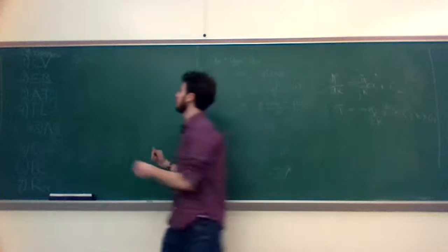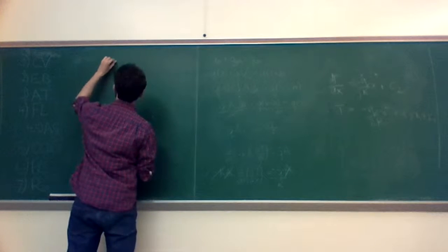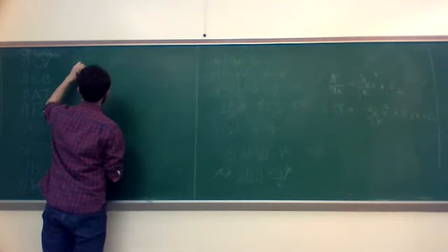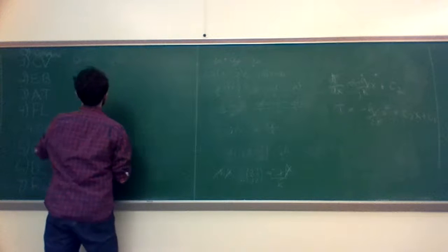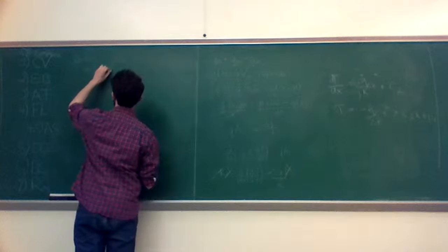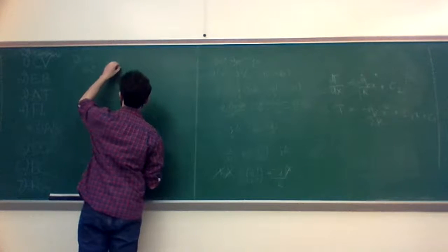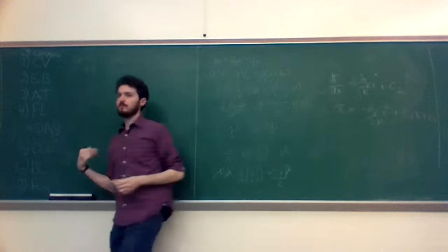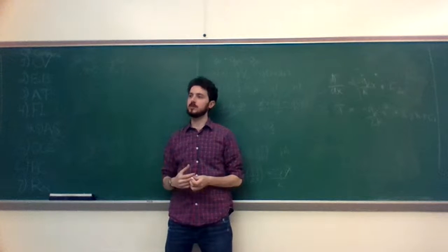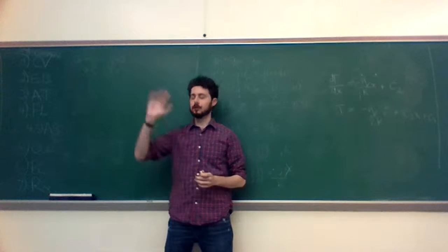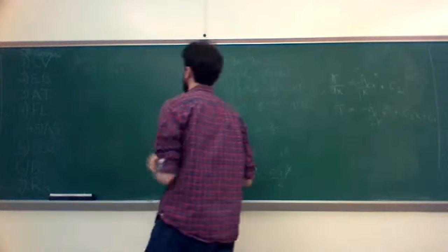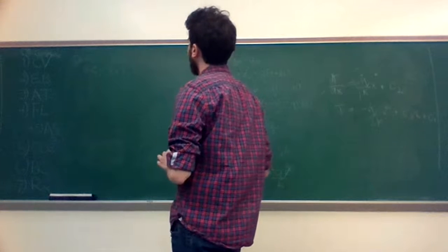Okay, so at x equals 0, we've got q equals 0. And at x equals L star, you've got T equals TS. It's something. We don't really know what it is. Maybe later we'll do some real problems where you've got internal heat generation and other stuff. Those problems are a lot of fun, I'll show you after. But it's some constant temperature surface condition. Just accept that for now. Okay.